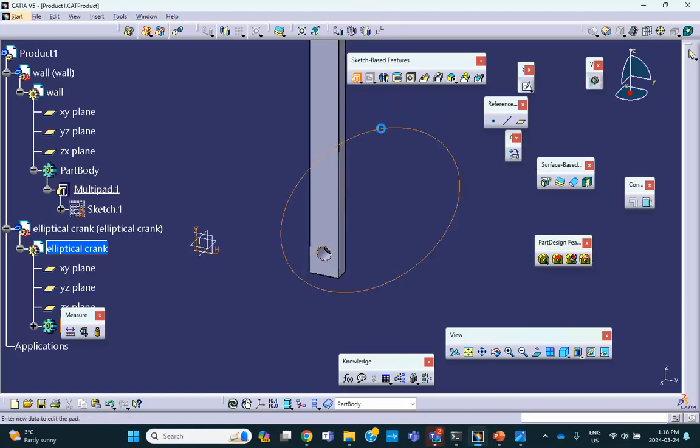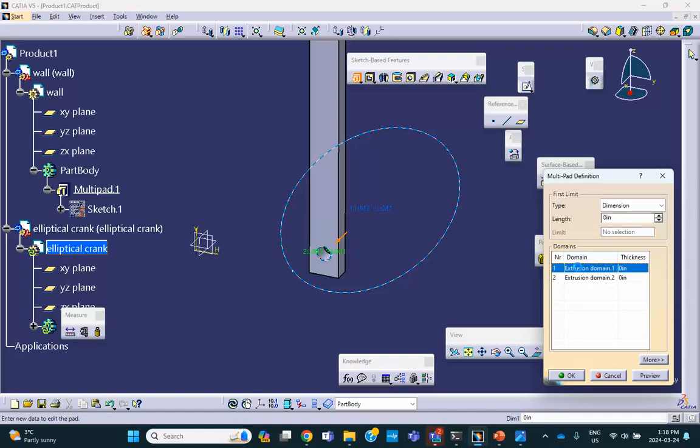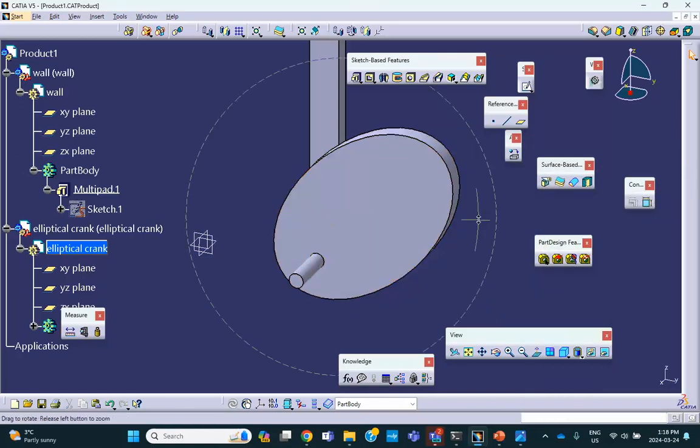Sketch. So this is the big ellipse, so I'll make that thing 1. Actually, I'll make it 0.5. And this is going to be the shaft over here or the pin over there. I'll make it also 2. Good. We go all the way to the top,